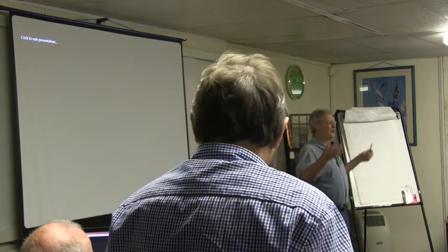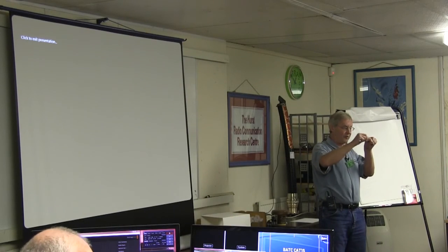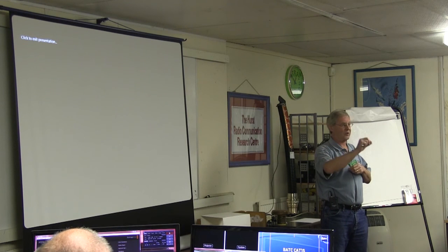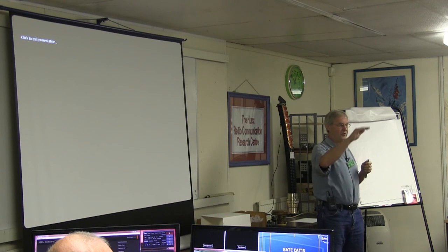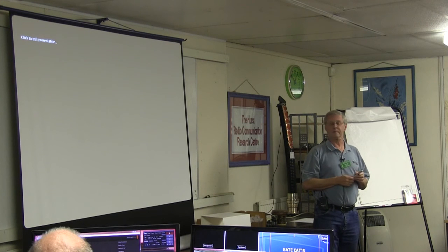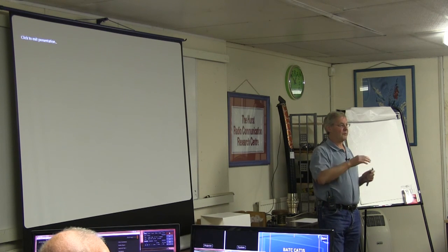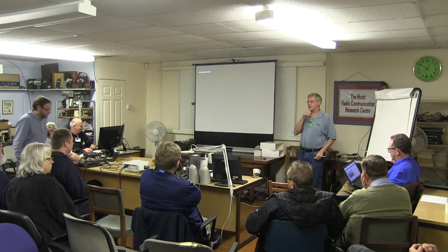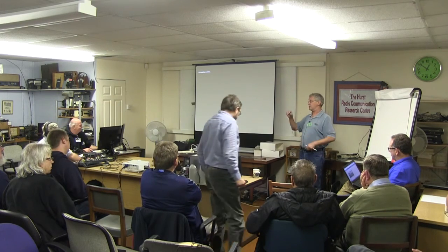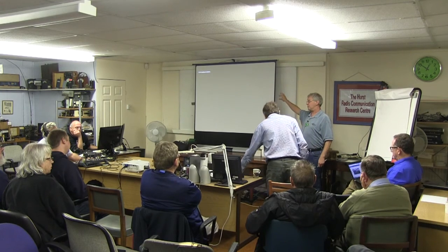So I kind of brushed the surface of it, but LCDs are much more complicated than they look. By the way, the 6 bits went to 7, to 8. Mostly they're 8 bits now. And it's very hard to do a gamma correction in the digital domain, because you just haven't got the fineness of correction if you try to do it with an 8-bit DAC, because the curves are very flat in places, so it's just too big a jump between values. There are some 10-bit LCDs around. Some of them are 10-bit linear. Now you can start to do the gamma correction back in the digital processing. So sometimes you'll get an LCD monitor and it's got a gamma adjustment. It goes in and adjusts these points on the curves.